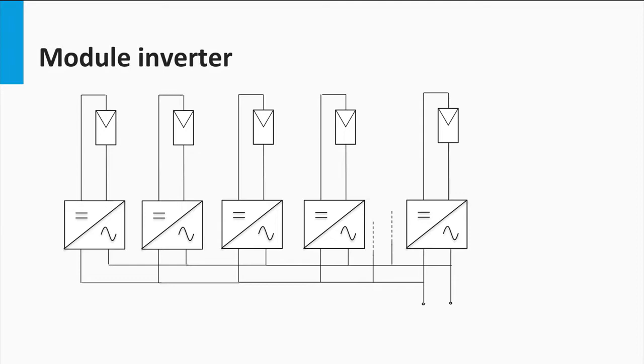Clearly, the microinverters provide the highest system flexibility, since extending the size of a system under this topology is far simpler. Furthermore, the DC wiring costs are greatly reduced. However, the investment and maintenance costs tend to increase, especially if the cost per watt peak are compared.